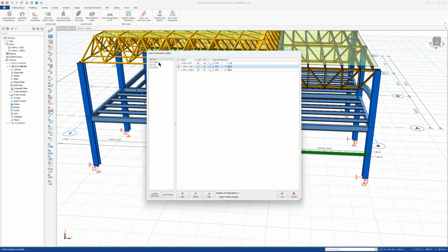the new interface. And we also brought you 4 different combination groups: ultimate limit states for concrete, ultimate limit states for steel members, serviceability limit state combinations for reinforced concrete, and serviceability limit state combinations for steel members. So we now have 4 different groups.